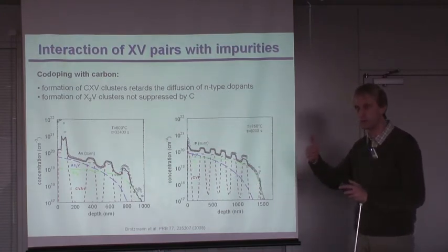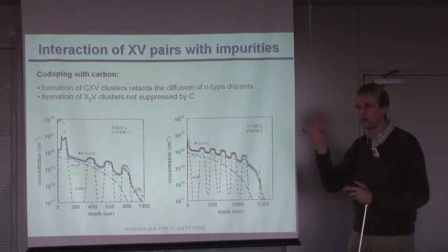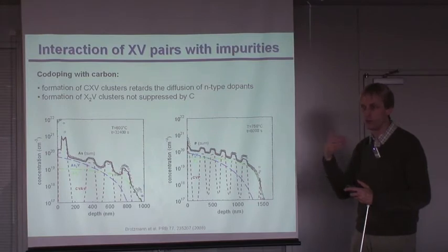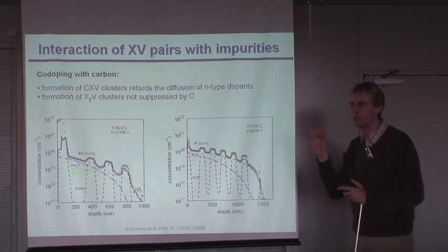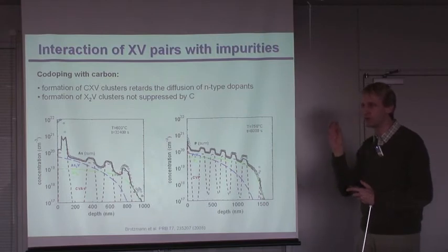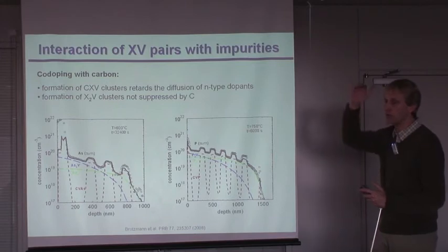And we're thinking about MOSFET structures, maybe source and drain regions, and you will shrink also in future this structure. You would like to have very shallow penetration depths. Maybe if you think about a germanium transistor, maybe as 50 years ago, but not with the contact transistor, but in the shape of a MOSFET structure. So with a source and drain, you need a very shallow dopant profile and high doping concentrations.